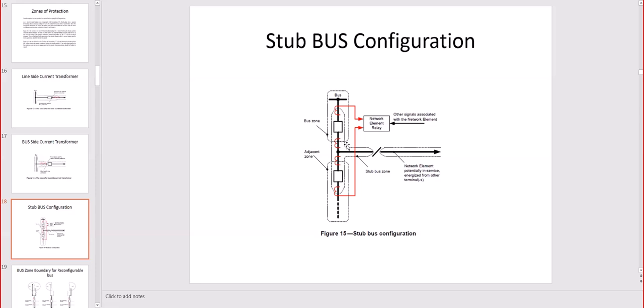And this time we still have another problem here. In this situation we covered properly the bus and the network or the load, minus this stub. If this is not a continuous bus to the load and you have a switch, that little portion from the bus to the switch is called the stub, and that is another zone. So we will see dedicated protection for that only, or it needs to be included somehow in the protection that you have from these CTs with a special arrangement.